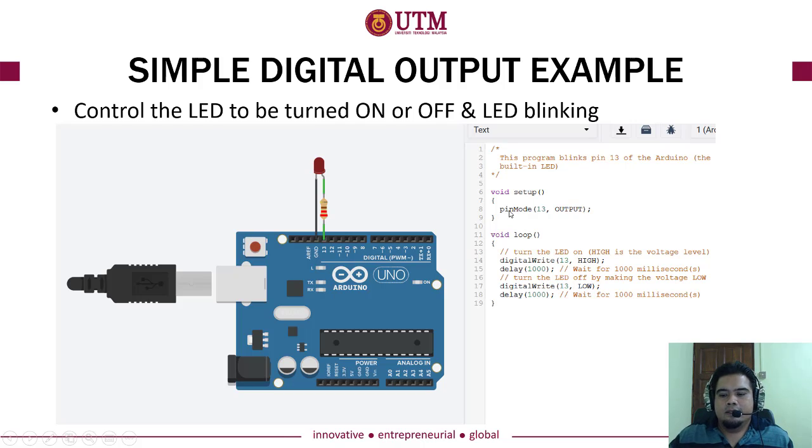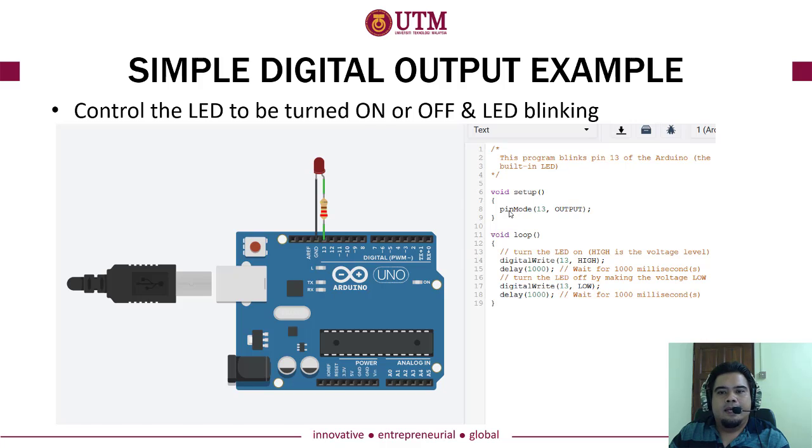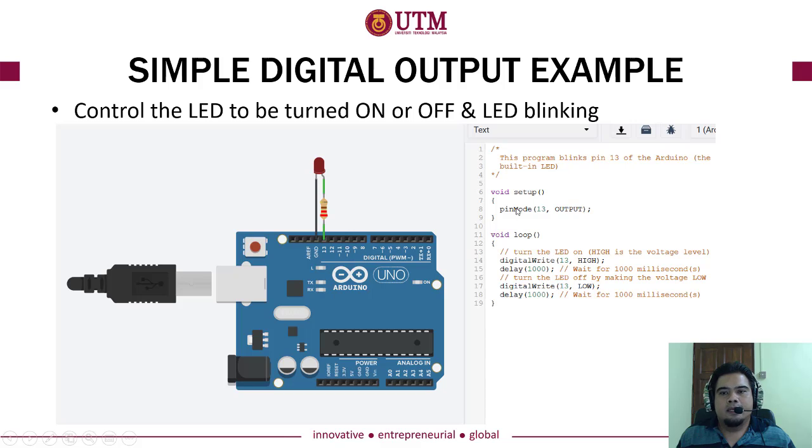Okay, and then again you can see pin mode. What is the purpose of pin mode? Whenever you want to use any port, you must first apply this function, pin mode, because this is what sets the port either as an input or an output. In this example, I choose pin number 13, so pin mode 13, so my pin number 13 I set as output. So that is how to use that function.